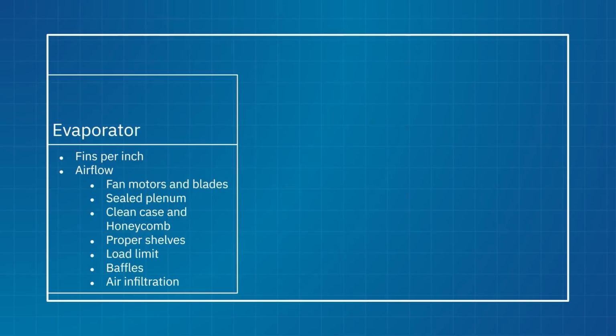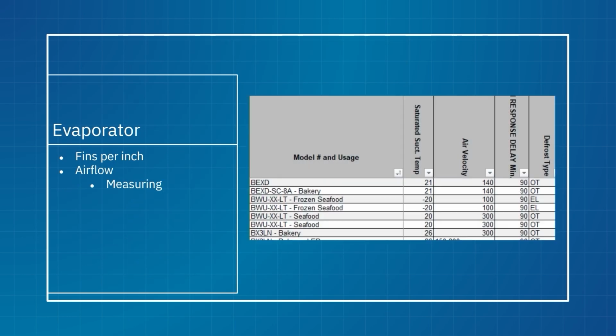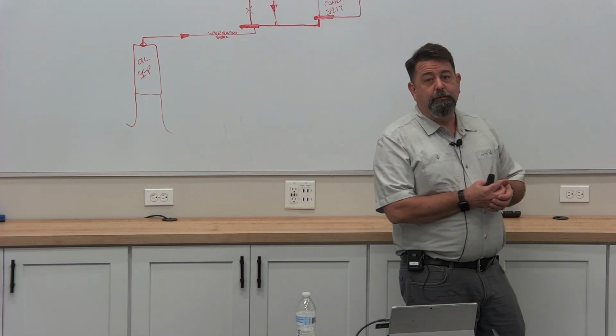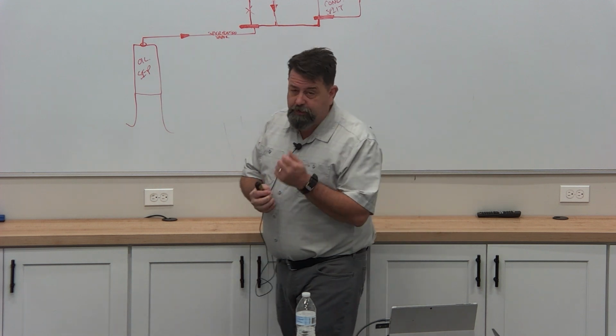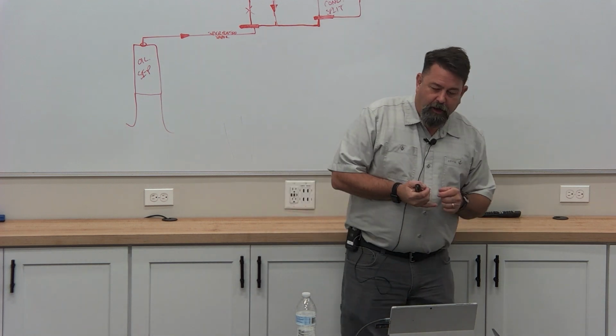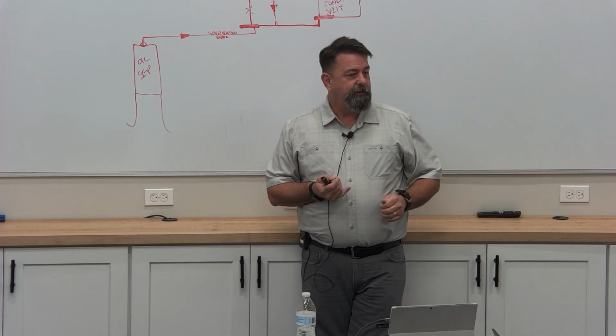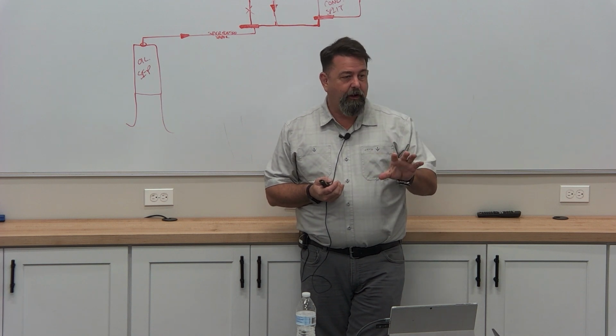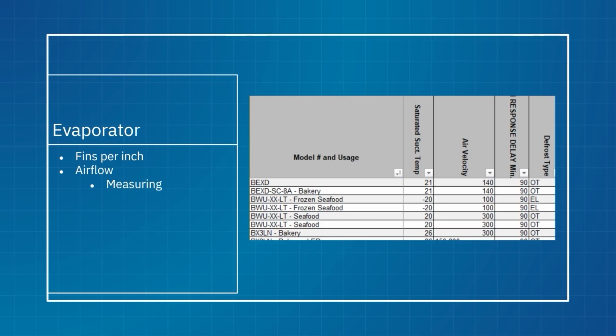All right, your back's not cooling. So somebody brought up earlier, how do we measure this? What are we measuring? Airflow. I got good news and bad news, right? The good news is the engineered spec, how much air I'm supposed to move through these cases. I can find that in a number of different places. The easiest by far is that parameter sheet that I shared with you guys last week. If you go to the parameter sheet, there is a section that says air velocity, and it's gonna have the manufacturer's airflow requirement. Now that number for us is cubic feet per minute.